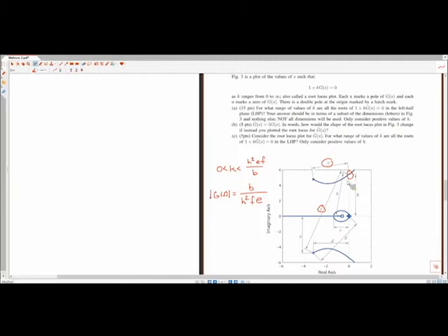And so we know that the K to achieve this closed loop pole location would be 1 over the magnitude of G of S. So then we just flip this here. So that means that as long as K is between 0 and H squared EF over B, then we know the system's stable. So there's a very geometric way in which you can interpret these root locus plots to try to understand what the value of K should be.